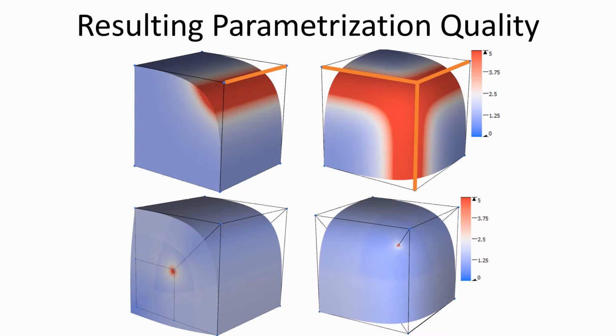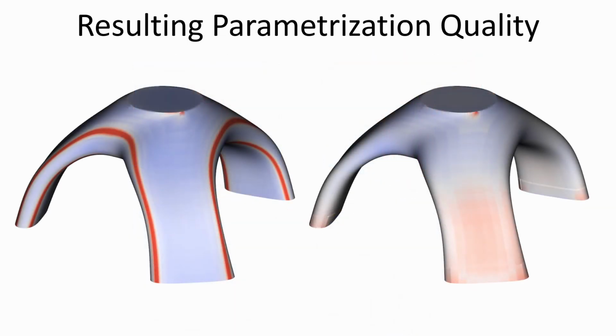However, away from the boundary and especially close to the newly generated extraordinary edges, the distortion has increased. All in all, the parametrization quality of the split model is much better than before. Here we show our results for the tripod model. Splitting the boundary cells resolves the singularities, but slightly decreases the quality throughout the rest of the model due to the larger aspect ratios of the split cells. Bisecting these cells improves the quality again.